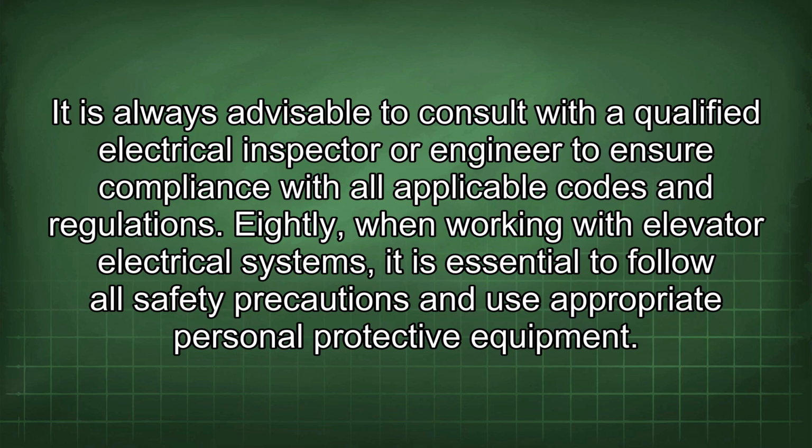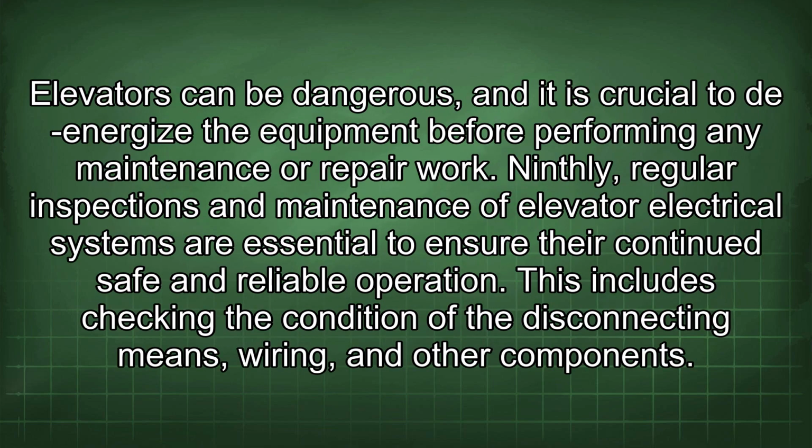Eighthly, when working with elevator electrical systems, it is essential to follow all safety precautions and use appropriate personal protective equipment. Elevators can be dangerous, and it is crucial to de-energize the equipment before performing any maintenance or repair work. Ninthly, regular inspections and maintenance of elevator electrical systems are essential to ensure their continued safe and reliable operation.